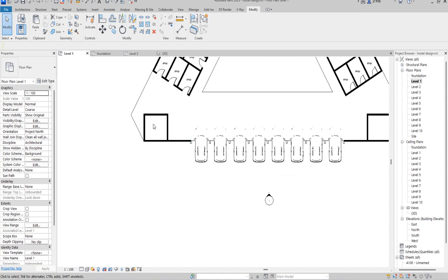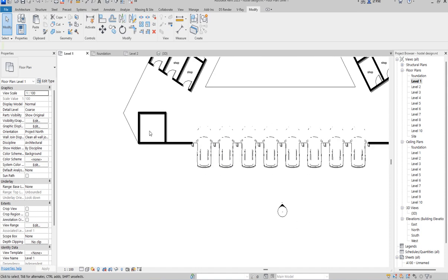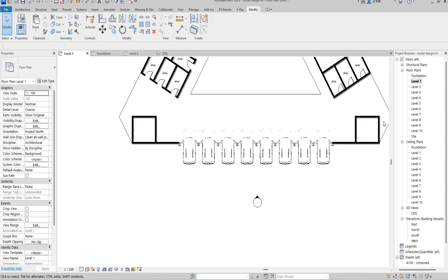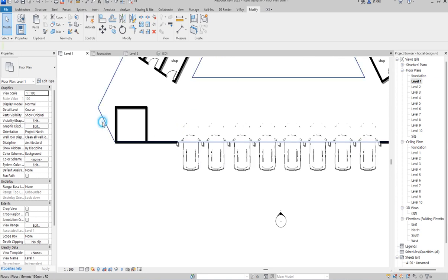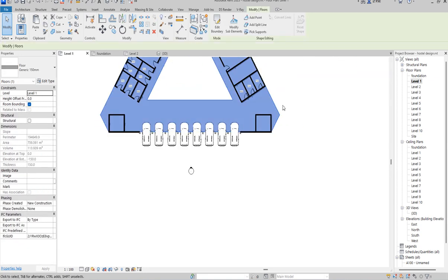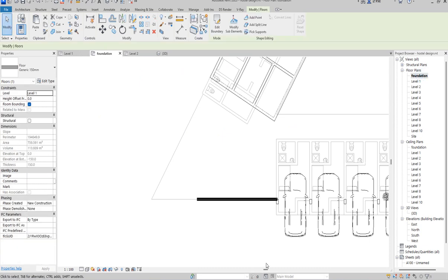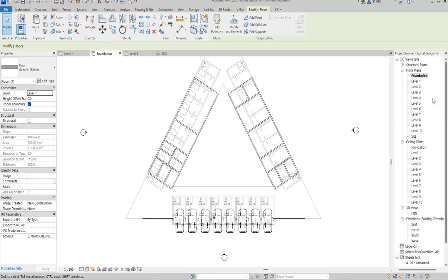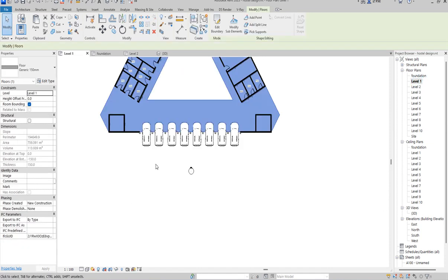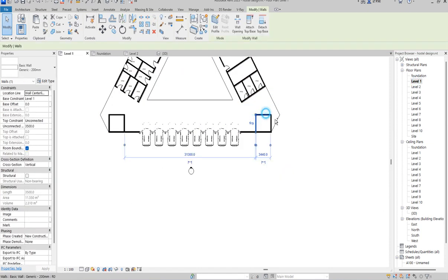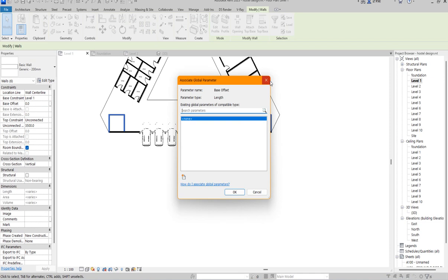So this is going to be for the surface, all the facilities like the stair hall and the lift side and every other thing. So this is having its own purpose. So now what I do here is that I'm going to open this one up. But when I open this one up now, it's going to be something that will affect the lower part. So I'm going to click here. So since I have that in place and it's not reflecting below, I will select everything here. Then say level, so move this one to foundation level.